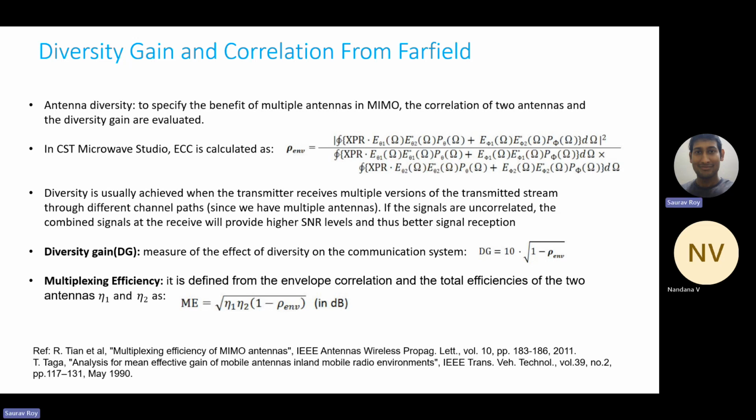That's why our anechoic chamber also has some bandwidth where it will absorb. In the lower frequency range, the wavelength will be higher. So if the wavelength is higher in that range, whatever irregularities or shapes we have designed in our anechoic chamber should be even more than that.